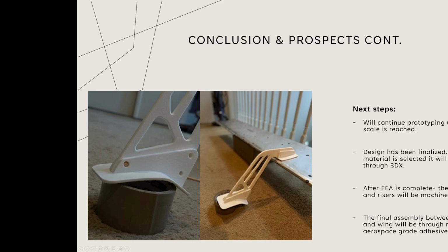But yeah, once the design's been finalized, I'll finish making all the proper constraints in 3DX, and then I will do the FEA. I'm planning on just mounting down, locking all of these mounting points, and making it so this bottom bracket, which attaches to the car, is not able to move. And then I will apply loads equally across this upper deck until either the brackets, the mounting hardware, or the upright gives out. So we'll see how that goes, but I'm excited for that part.